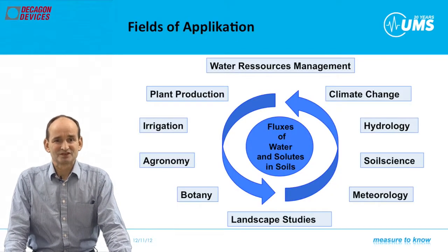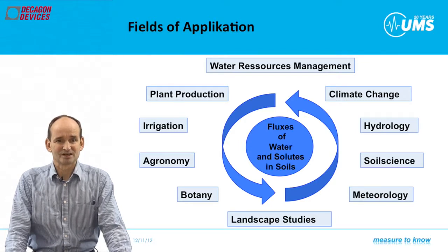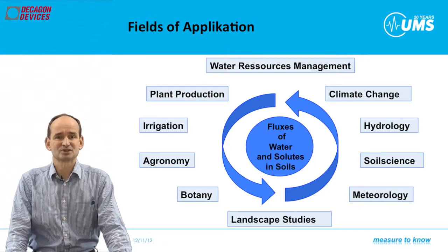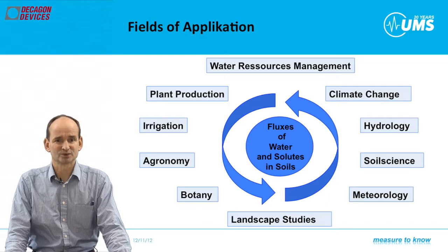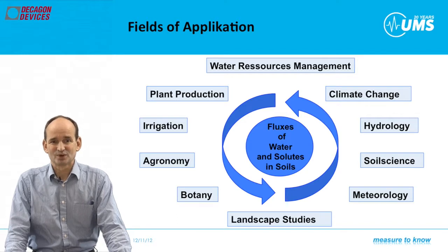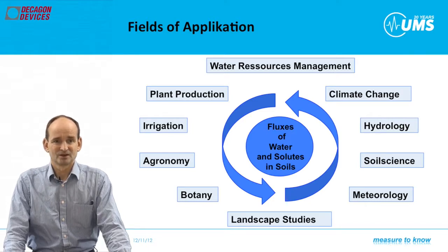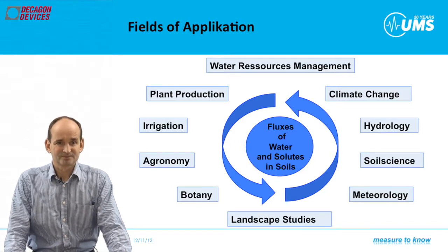Therefore, we use smart field lysimeters for water suppliers and hydrologic research as they give both pieces of information: atmospheric input directly and the continuously changing soil surface and groundwater recharge capability. They also work at sites with a negative water balance, which means evaporation is higher than precipitation. We may use them for climate change projects.